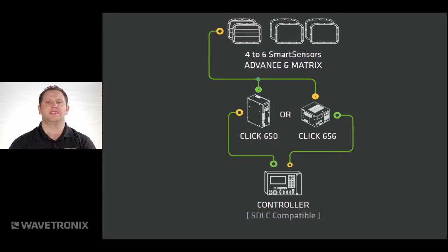So the controller does need to be a NEMA controller in most cases. There are some 2070 controllers that have the 2E I/O card with firmware running to be able to receive contact closure, or to receive over SDLC. There's some pinout work. Anyway, our people at support can help you with that.